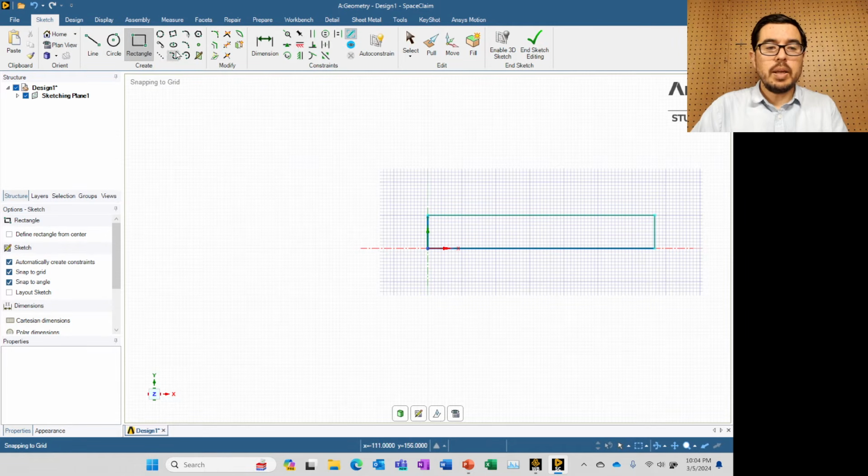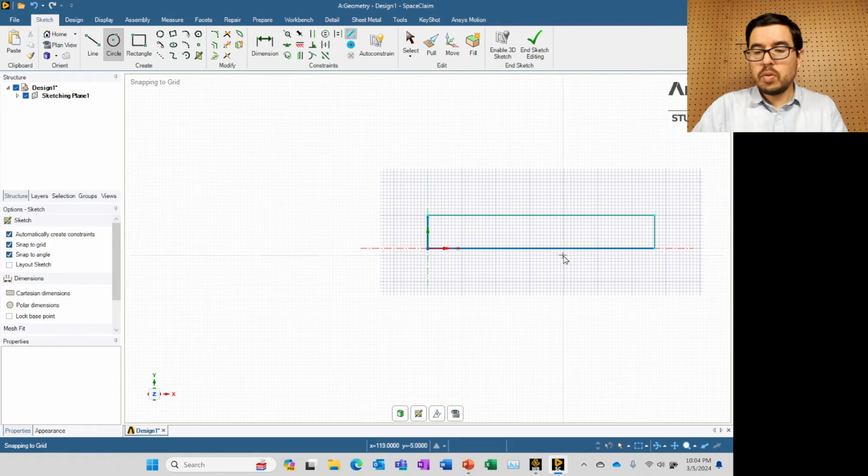We will go ahead and add that semicircular core region. I clicked on circle. Now we see there's a midpoint option appearing here. Bring this out like this. The diameter we want is 25 millimeters, which corresponds to the 12.5 millimeter radius. So just 25 there.